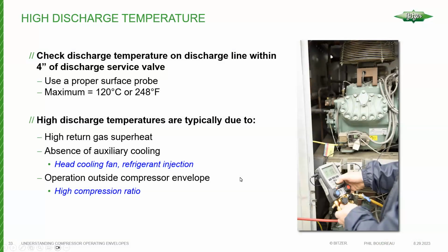One of the other benefits of a valve such as that is that you can expect a quicker response time due to a smaller sensor. When you have a smaller sensor, the temperature of the sensor can change more quickly. Whereas if you've got a great big bulb on an expansion valve, that tends to take a little longer to warm up and cool down as the refrigerant flow varies through the expansion valve.